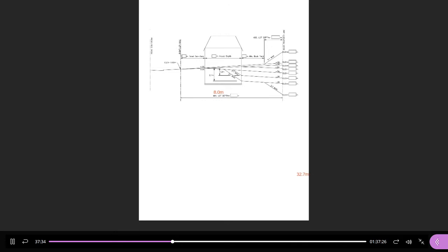The zoning will tell you how close the building can be to the front of the lot, but then we usually push the split point. What I'm trying to establish is if the front of the building is here, then the split point at the front is covered. If the building's a little further forward, that's fine. The front yard must drain away from the building. You can't have water from the street line draining toward the building. Okay, that's not allowed. You can't drain from here toward the building. It always has to be higher at the house than the street line.